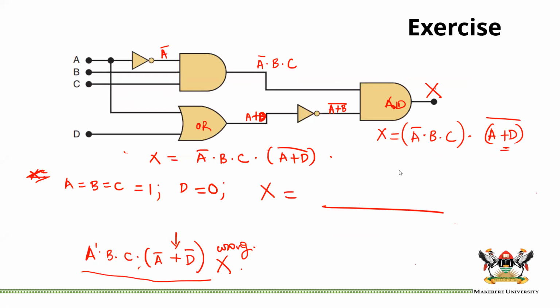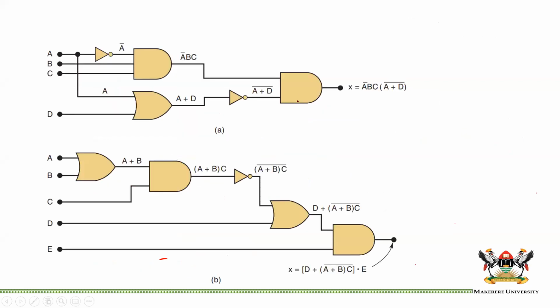The reason is that you have a 1 or a 0 here, and you have an inverse. So 1 or 0 is 1, inverse is 0. And when you put a 0 here, it makes everything a 0. It wouldn't matter what it is. And you can see that obviously you got them correctly. These are very complicated diagrams, but you have got it very easily, which is wonderful. And that's the beauty with digital electronics, that no matter how big something is, there are very simple principles that you can use to get it correct.